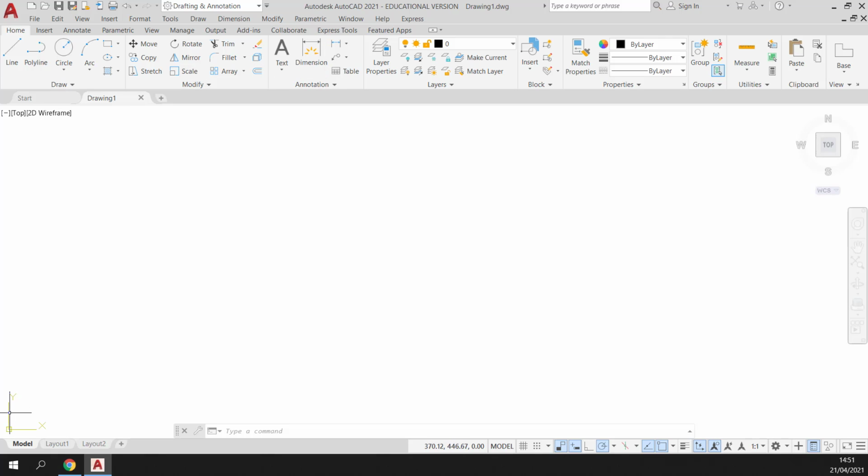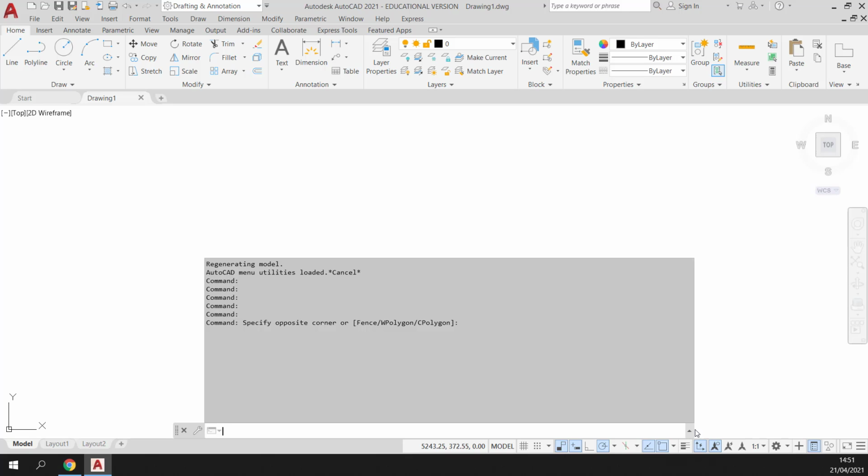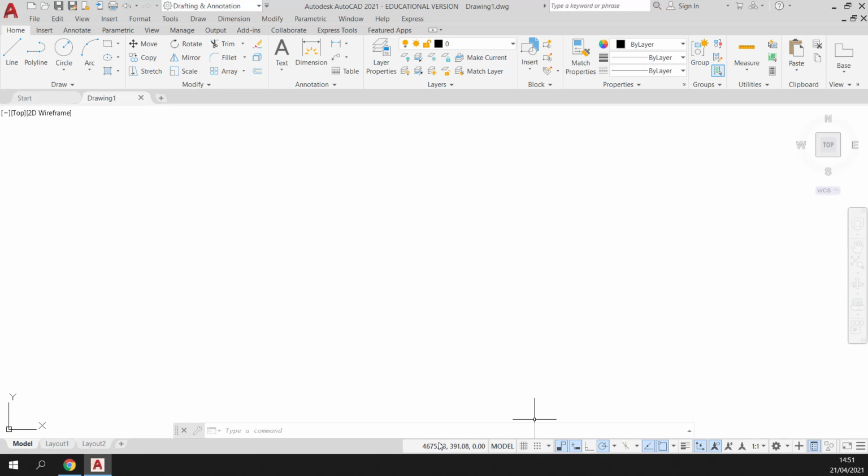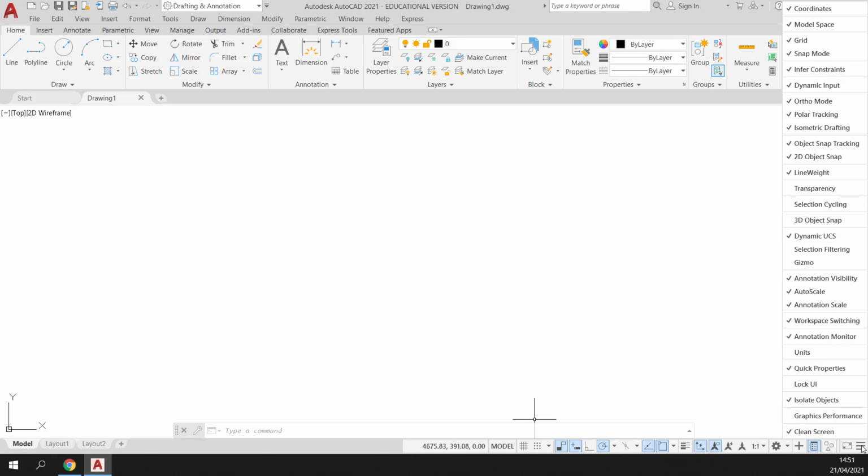So there's that little ribbon. Down here then we've got the UCS icon and display origin. We'll again talk about that a little bit later. We've got our command window down here as well, and you can expand that up. But I suggest you keep it down to one line if you have it on at all. You can also expand it using that little arrow. And then your screen may look a little bit different at the bottom here at the status bar. There is a three little lines customization option here. As we go through the course, I'll show you a few things that pop on and pop off that might be useful to you.